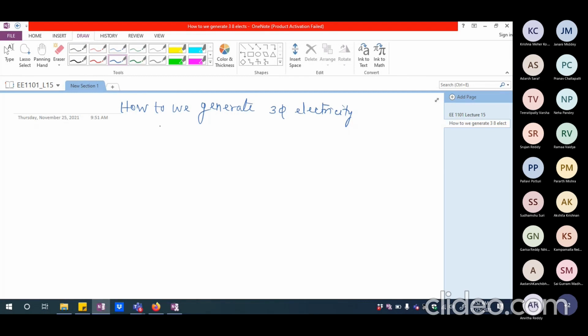Okay. We will look at the connection of 3-phase. That will make things clearer. We are not talking about the length being smaller. We are talking about the number of conductors that you use being lesser. In single phase, you have to use a forward and return path. Whereas in 3-phase, you might actually have the freedom of using one of the phase conductors as the forward path and the other one as the return path. It is possible. Okay. So we look at how the connections are made.